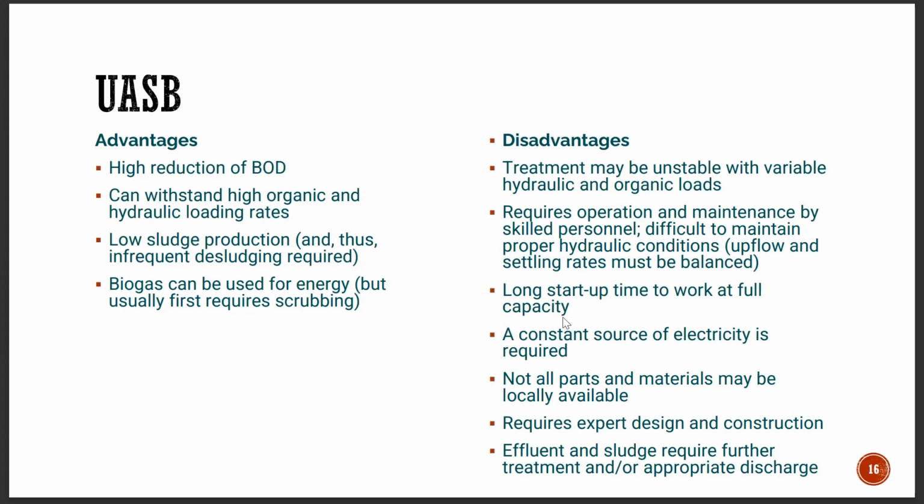Then at full capacity, the UASB reactor will take a lot of startup time. And we may require a constant source of electricity for allowing the water to enter the reactor. It needs to be pumped in because the water has to be upflow, right? Then not all parts and materials may be locally available, so that can be an issue. Then the design and construction of this also requires expert opinion.